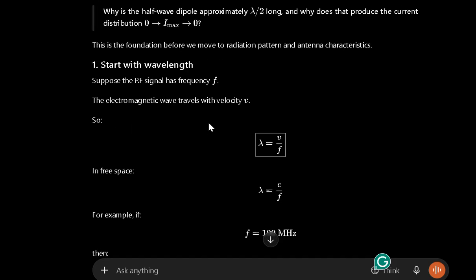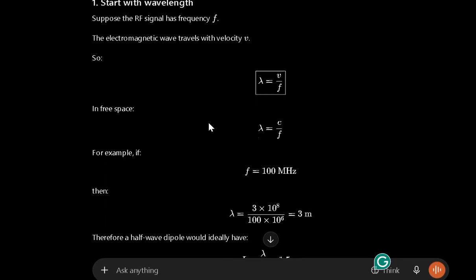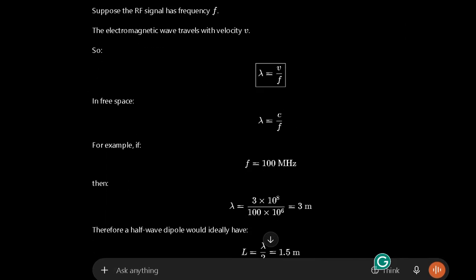Okay, we start with the wavelength. The RF signal has a frequency f. What is the wavelength formula? Where v is velocity, lambda equals v by f. This is the formula for wavelength. In free space, lambda equals c by f. For example, if f equals 100 megahertz, then with the speed of light...